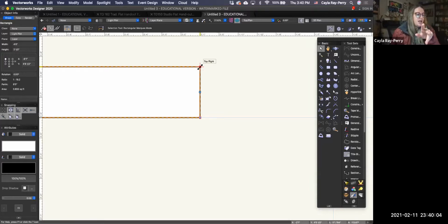If you get a line like this, a diagonal line with 2 arrows on either end, if I were to click and drag, that's going to reshape my object. Like that would be me saying, I want to grow this longer. So I could grab this midpoint, drag it out, and you can see that the width of the object is actually changing. I don't want to do that because I want it to be at 4 feet.